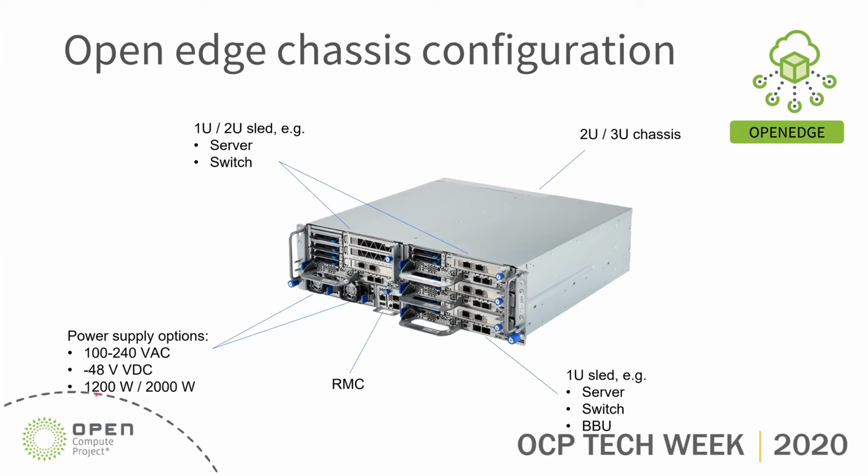And also another key point of matching the power capacity to the need is that the PSUs can operate at the more efficient operating curve of the PSU, so more efficient use and lower energy costs.